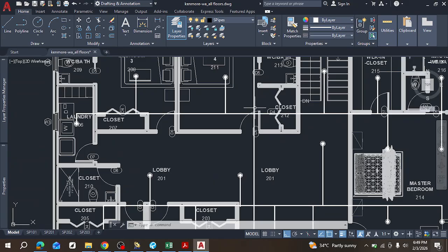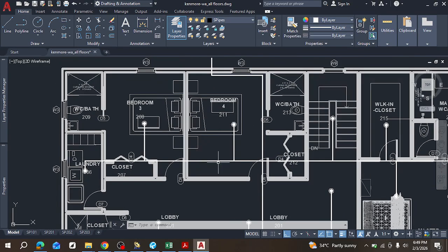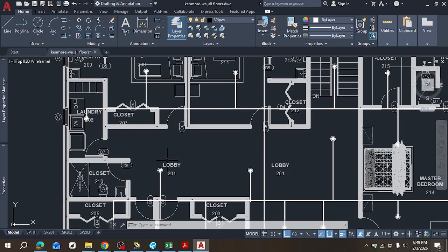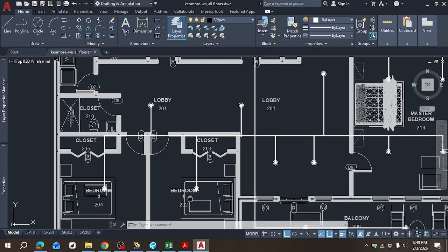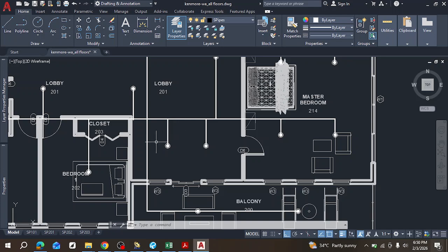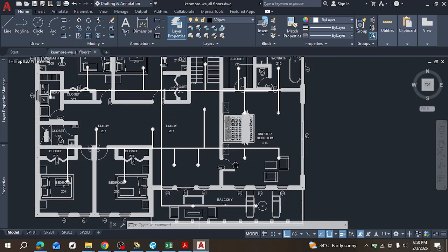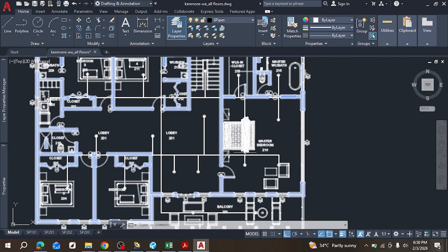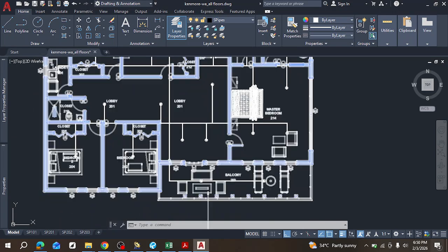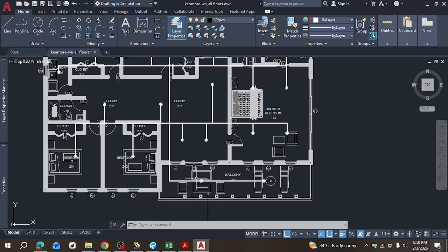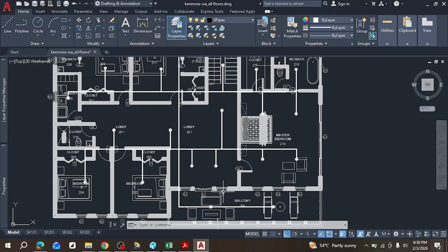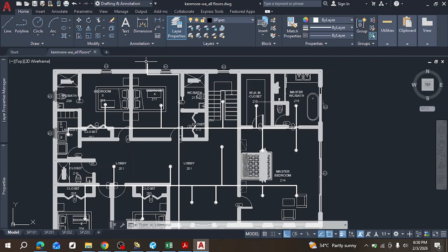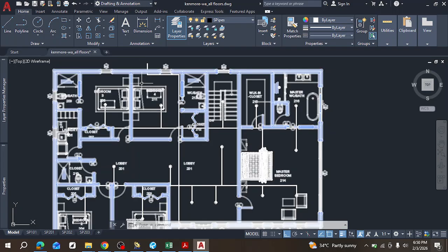Now this is another critical junction, right? And then it comes here, supplies this guy. Oh, there's a lot of bedrooms in this building. Right? Supplies here, and the end point now, or the farthest point, I'm starting to see. I've started to identify the remote area, right? And that appears to be here because this is the farthest point away from the riser. When I say the riser, I'm referring to the setup that permits water into the house, right? And that is around here.